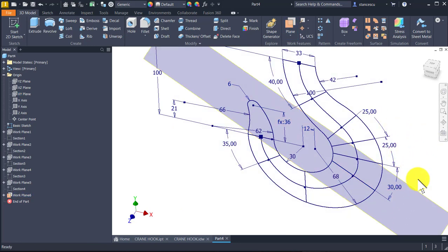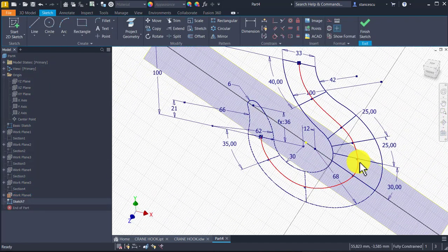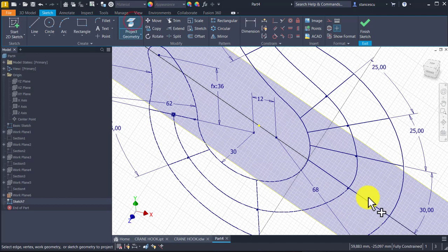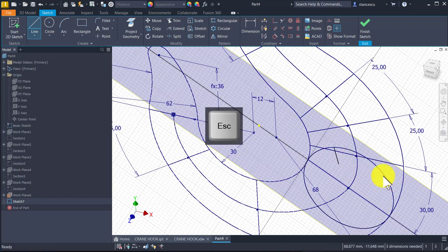Diameter, new sketch, F5, project diameter, make it as construction to have no problems, then a circle from the midpoint to one end of the diameter with green, two lines. The first is wrong.